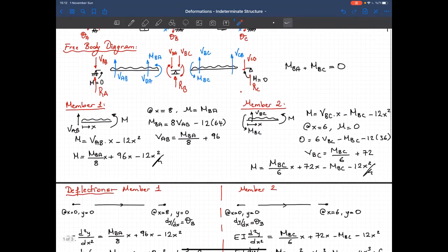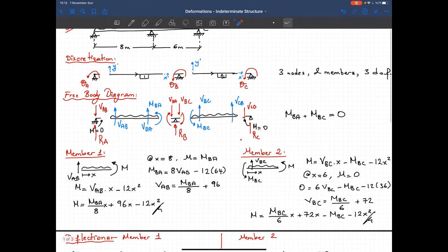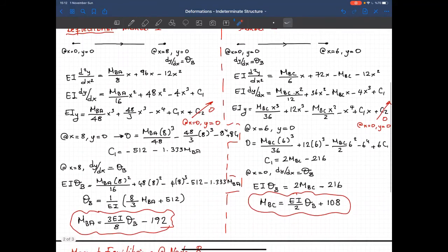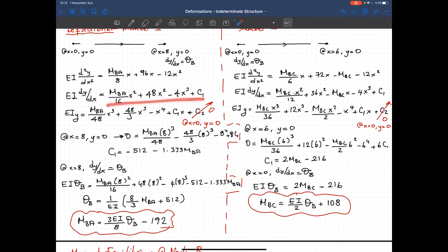If you think about our solution, at the end of the day, we use the end deformations for every member, or the degrees of freedom in the structure, and we use only the end moments. And by using the differential equations, I solve everything for this member. I obtain the full rotation equation. I obtain the full transverse displacement equation. But at the end of the day, I use these two equations just to calculate the relationship between an end moment and the end rotation.